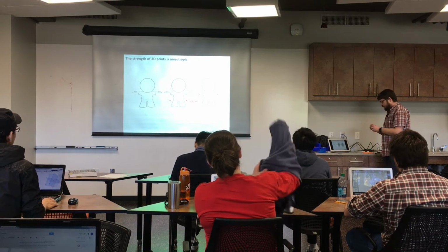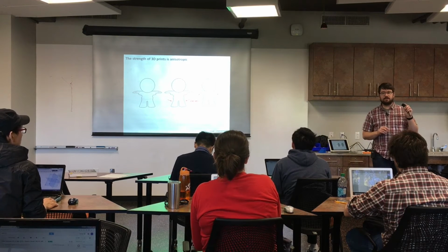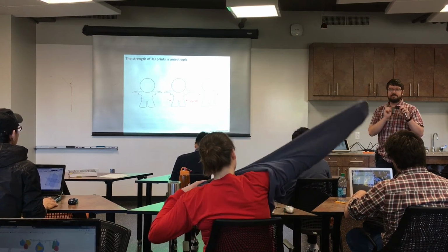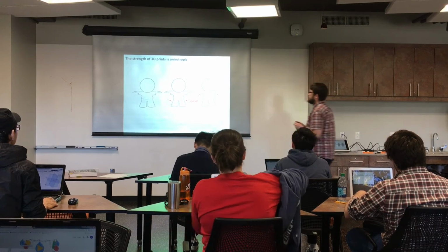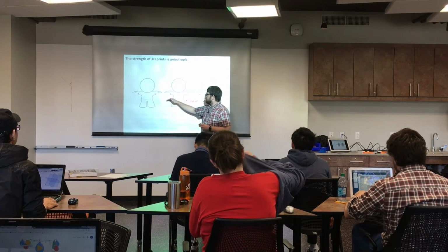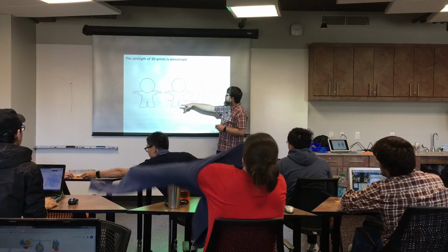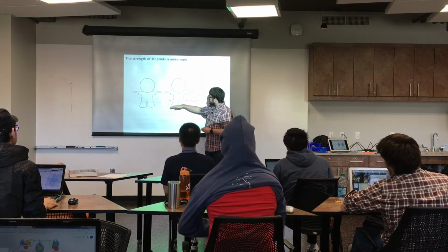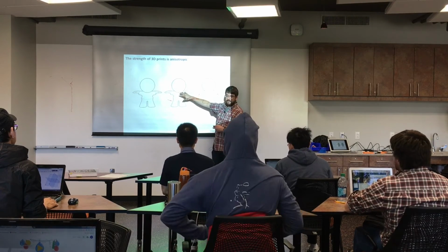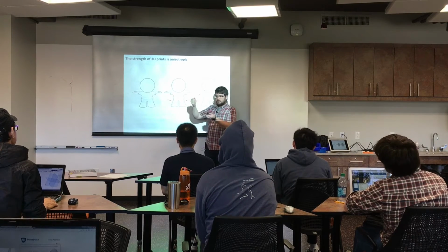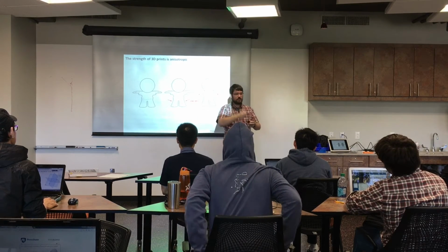A big one to consider is that the strength of this part is not isotropic. It is printed in layers, and it is the weakest in the plane of whatever the z direction is. So for example, if we printed this little person figure standing up like it is, the z layers would be like this, and it would be pretty easy to shear the person like this, but not vertically.